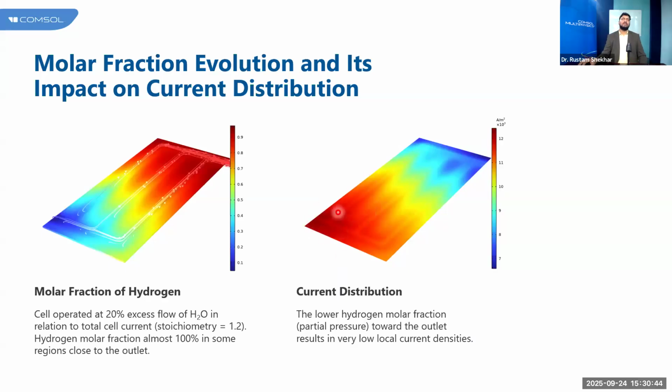Initially we have higher current density because we have more fuel that can get converted, but along the flow the fuel will get reduced, meaning here the H2O is reducing. So at the later part we don't need to deploy as much current, and still we are getting higher hydrogen mole fractions. What we can confirm is that the flow is uniform, but the conversion is not uniform. We started producing hydrogen from this place, and until the outlet we are producing hydrogen, but spatially there is a variation.